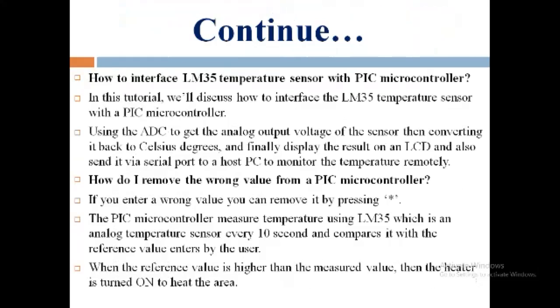Then the second question is how to interface the LM35 temperature sensor with a PIC microcontroller. In this tutorial, we will discuss how to interface the LM35 temperature sensor with a PIC microcontroller using the ADC, that is analog to digital converter, to get the analog output voltage of the sensor, then converting it back to Celsius degrees, and finally display the result on an LCD display, and also send it via serial port to a host PC to monitor the temperature remotely.